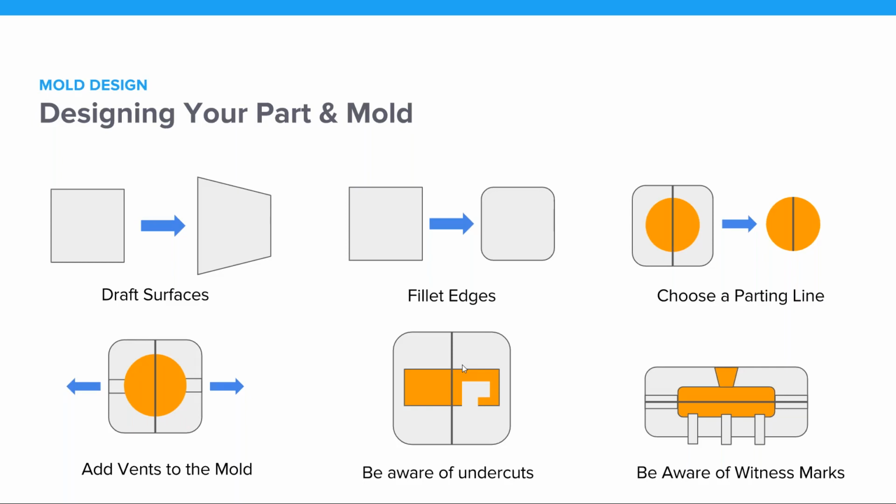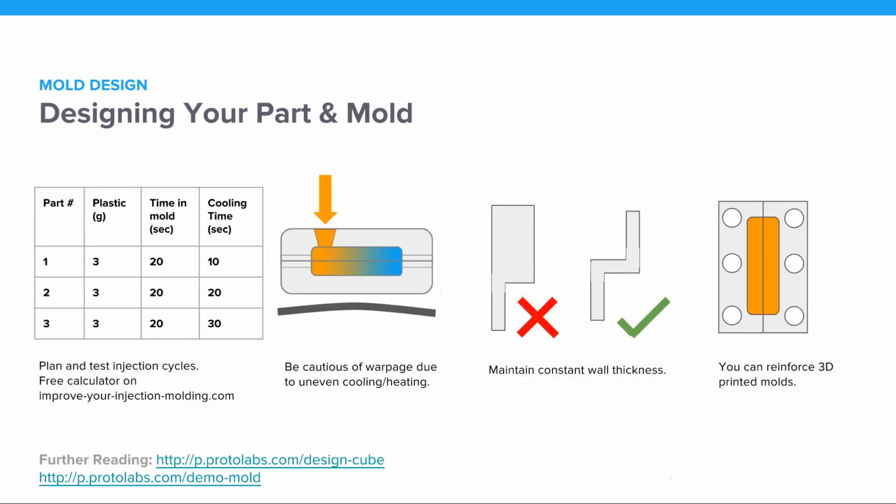It's where some part of the mold leaves a blemish on the part. Some of them are unavoidable, so you just have to either sand them down or make sure they're in a hidden spot. If you'd like to see a witness mark, find some plastic pieces and turn them over on their backs, and you'll often find little circles indented into the part. Those are ejector pin marks.